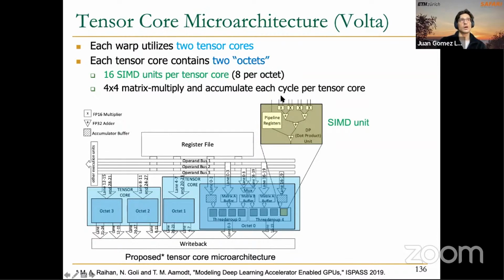As you see, it has 4 inputs. Here we perform the dot product operation of 4 input values. Each of the SIMD units computes a 4x4 matrix multiplication, and can do it essentially in one cycle. That's extremely efficient, because we also have many of these SIMD units.